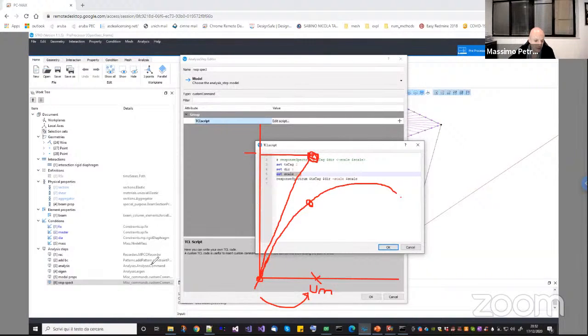This is the reason why I'm using the scale factor. Imagine that this is the total displacement computed by the response spectrum. I scale it by a small factor, let's say 10 to the power of -3. So I have this displacement here, U modal tilde. A small displacement. This will give me an almost elastic stress, which is here.